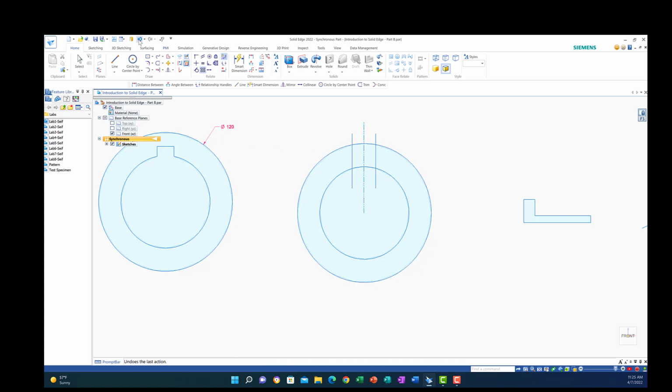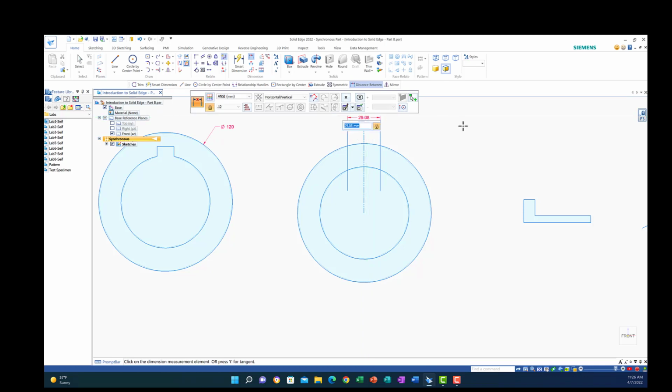If you want to do the opposite, around this line, I need this line to be similar to this line, so it's going to make it wider. Now I can fix the dimension after that by putting the X dimension between this line and this line. If I want to put 15, it will arrange both of them because they are symmetric around the line.